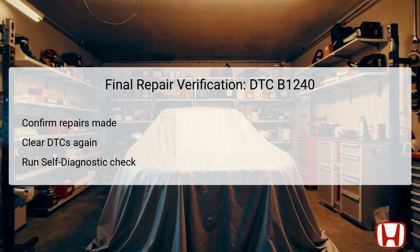After completing the necessary repairs for DTC B1240, it's important to verify that the repairs were successful. Begin by confirming that all connections are secure and that the components have been appropriately replaced or repaired according to the previous troubleshooting steps. Once this verification is done, clear the DTCs once more using the Honda Diagnostic System, HDS.